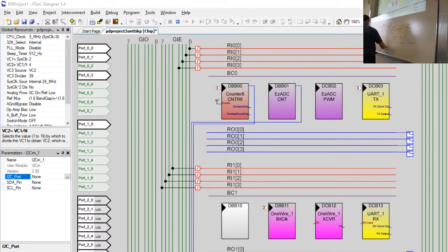SPI device. Okay. Chip select. Clock. Master in, slave out. Master out, slave in. Could be that there's only one of those actually on the device. Our device is the A to D converter, MCP 3201, a 12-bit SPI AD converter,